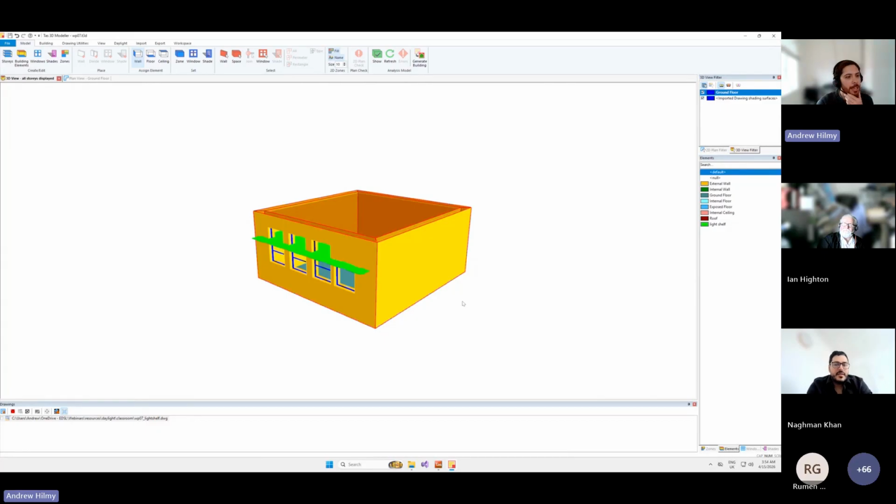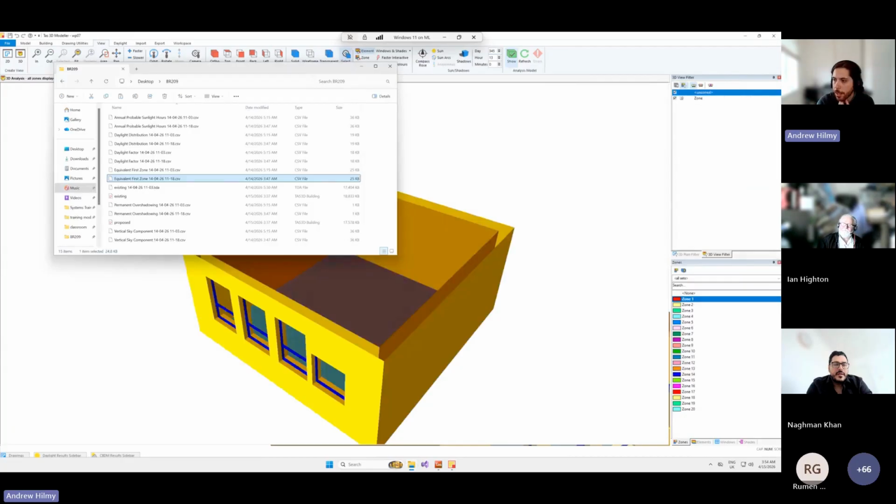when you import a 3D DWG, it doesn't necessarily have windows in there. It might just have holes where windows should be, for example. But then what you can do is you can select a surface which contains one of those holes, assign it to a story, and then add a window in TAS where that hole is. Right. And then you can analyze it. So there's a way of doing it. Yeah, there is a way.